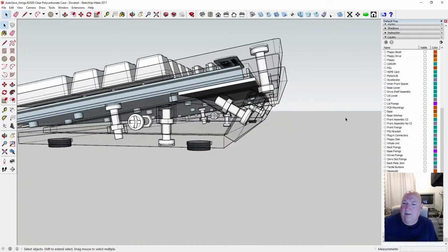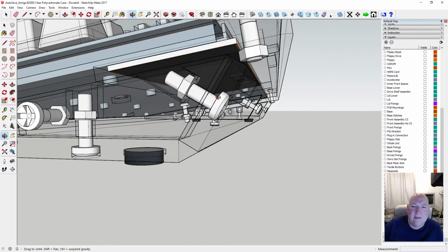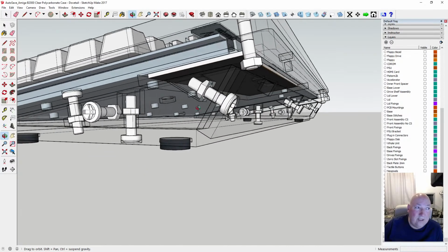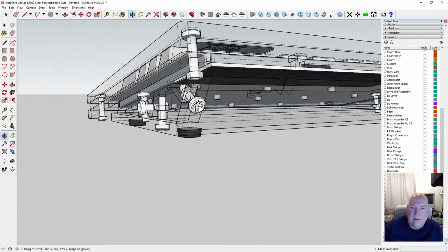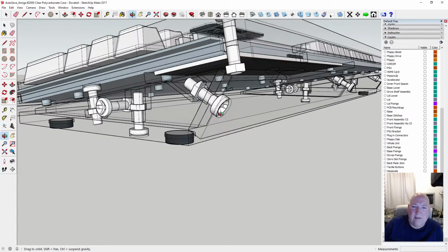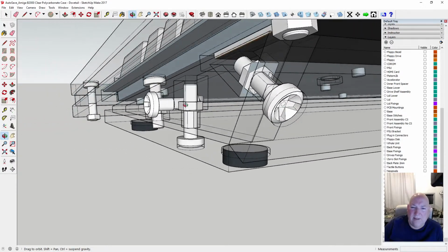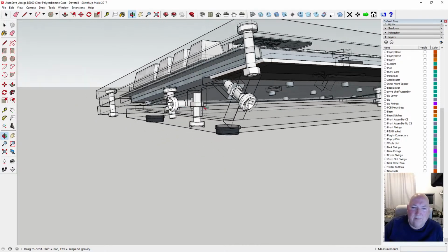I use decorator's blue tape, 50mm by 50 meters, from the tool station, I don't mind saying, and a little pot of super glue. So you tape both sides, super glue it down to the bed, and that's what I do.